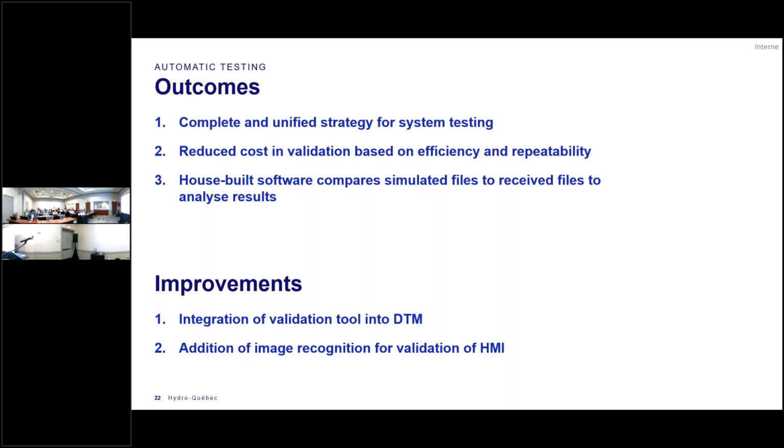I think it was done a bit more thoroughly than what was done previously at Hydro-Québec, meaning that we were validating as well the behavior of the IEDs based on the Goose publication, subscribing, and the MMS reporting as well. Something that beforehand, I think it was just the behavior of the IED, and not with its communication components validated at the same time.